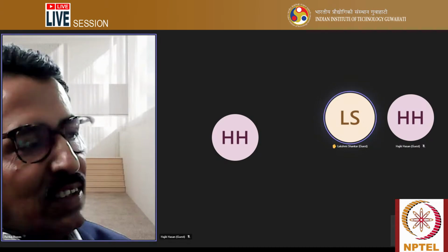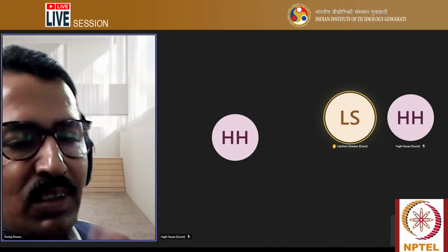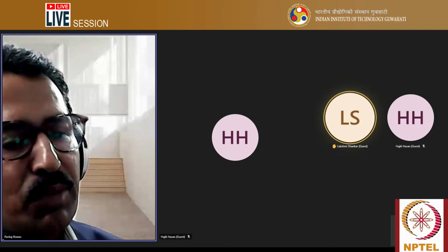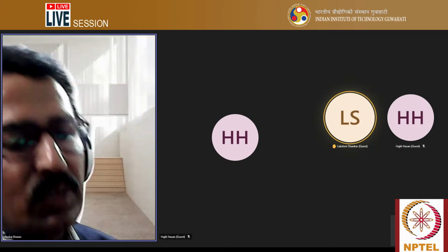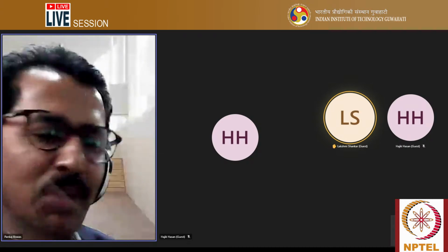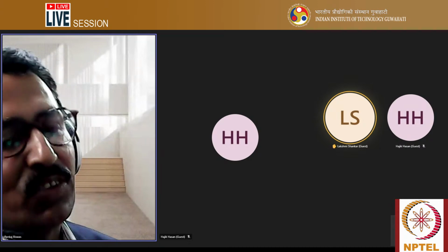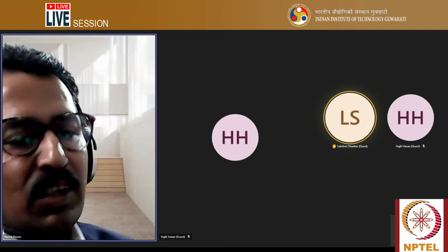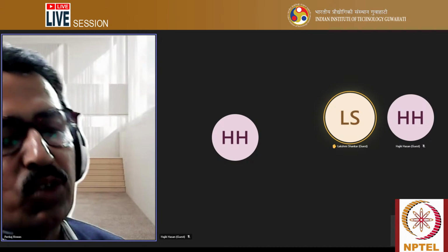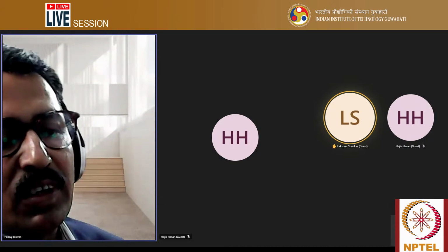Like, cellulosic: where is it applied? For which position is it preferable? Then why is the basic electrode coming? What are its basic features? What are its drawbacks? Everything you can get. The basic electrode is generally meant to eliminate this hydrogen effect. You can call it a low hydrogen electrode, or a hydrogen free electrode.